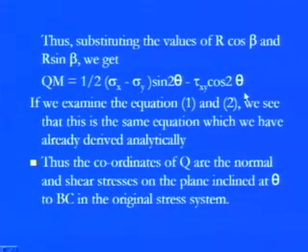That means if you want to calculate either this sigma n, which is the sigma theta, or qm, which is the tau theta, you have the combined effect of the real form of the stresses, that means sigma x, sigma y, and tau xy. Because of those there is a rotation, and that's why this theta angle is there. So calculating either the normal stress component or the shear stress component at the oblique plane is pretty easy, and these equations are well established.